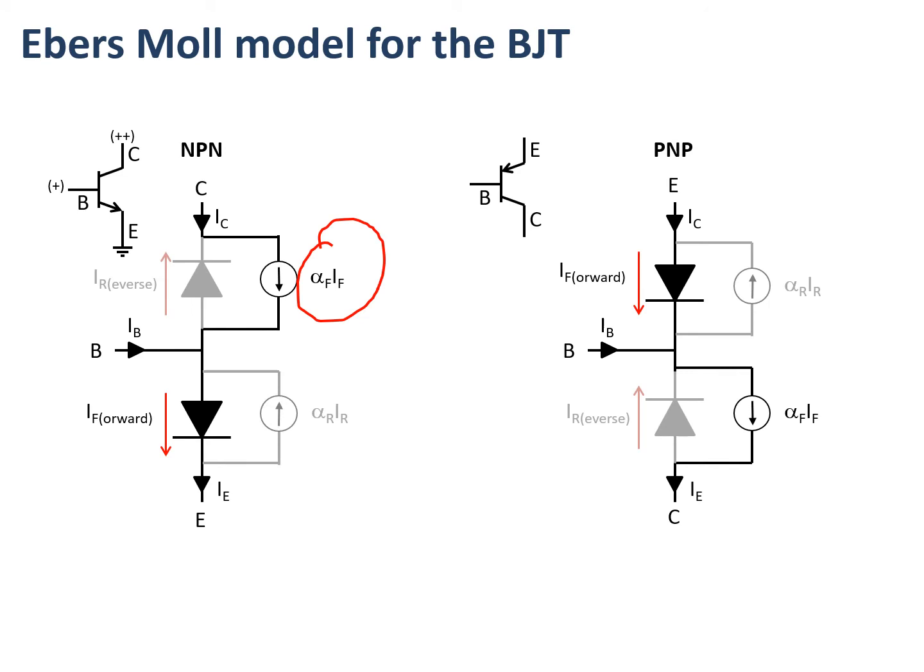So as we've discussed, what's really important is this use of the base current to create a much larger current flowing between the emitter and the collector. Now when we do a conventional circuit diagram, we generally draw positive current because that's the way that historically we started to draw electrical circuits. So in this diagram, for example, on the left I've got an NPN transistor. My base current comes into the base and it controls the much larger current, the conventional positive current flowing from the collector to the emitter.